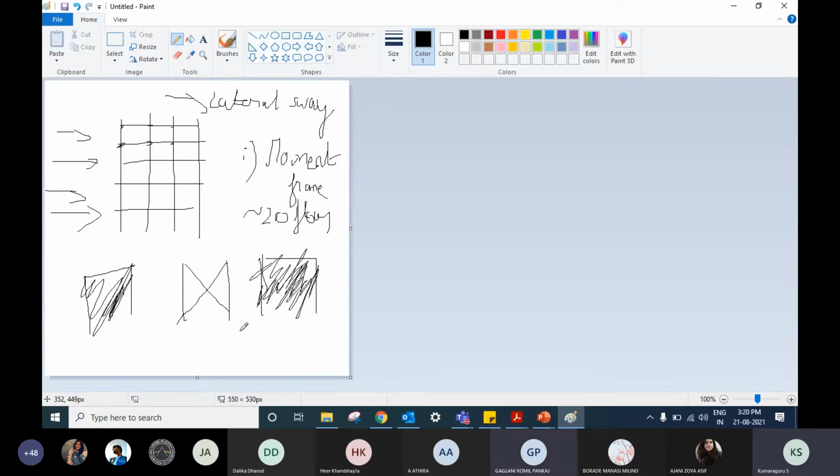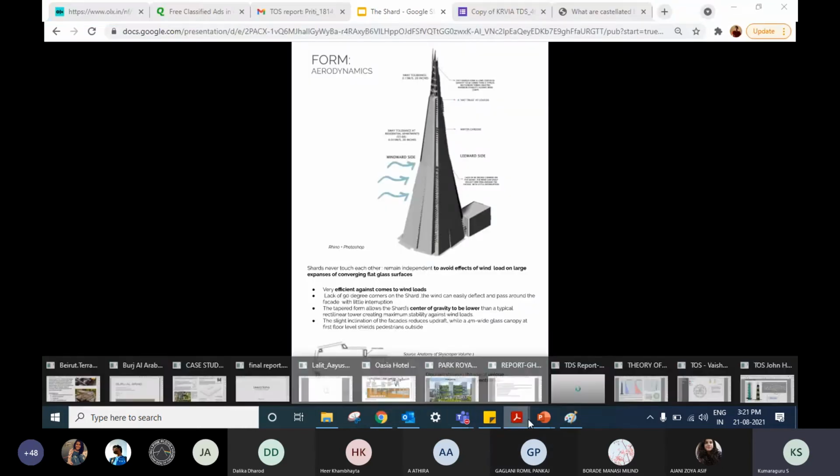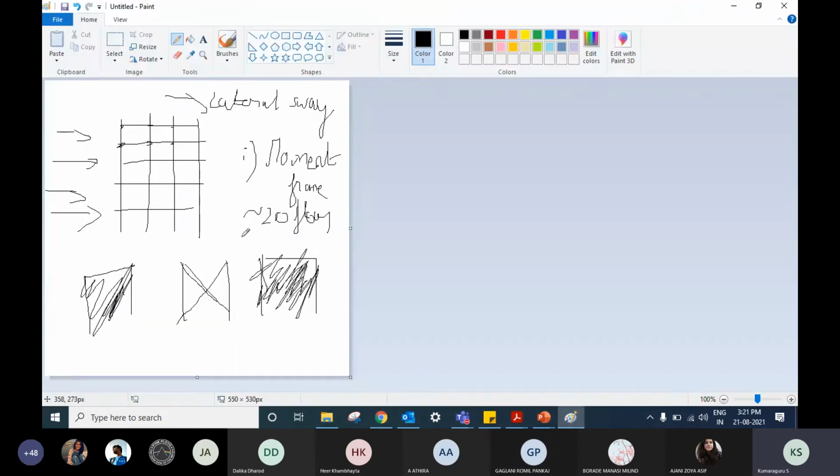But you would have seen when you add bracings, which are massive bracings, as in this particular project, these are not small bracings running from individual column to column or individual floor to floor. These are running across several floors, so that forms a very, very rigid system, and your lateral sway is much more effectively taken by it. That's how you are able to go much taller.